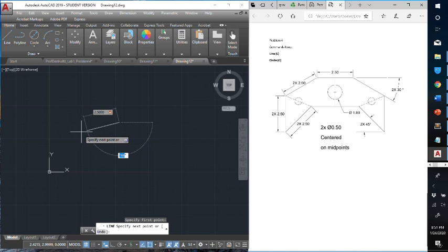Now when you hit tab, it usually allows you to put in an angle, which is exactly what I want. See, there's a little padlock symbol next to the 2.5. When I hit the tab, it's saying that the 2.5 stays constant, and now I can adjust the angle. Now I can also see from this dotted line over here that they're measuring it from the positive x-axis, so an axis moving horizontally to the right. Now if I were to draw a line that comes from here to here, from the positive x-axis, which let's imagine is this horizontal line, what would the angle be if it's 45 degrees at this corner?